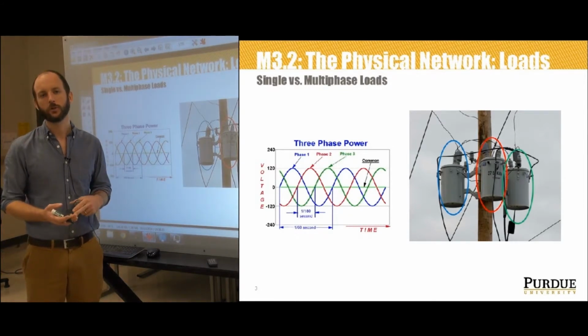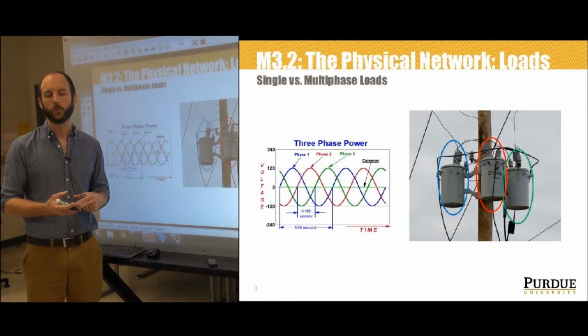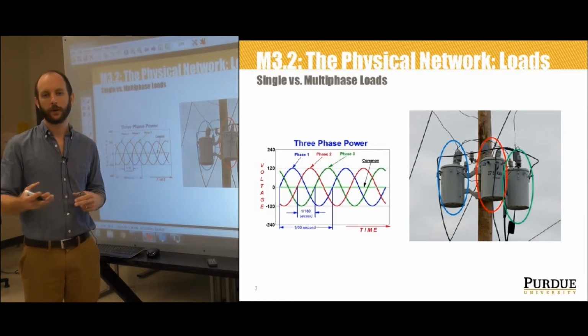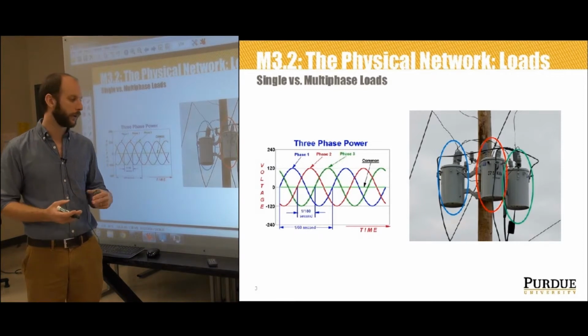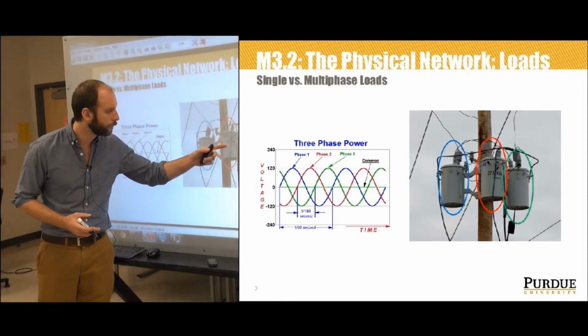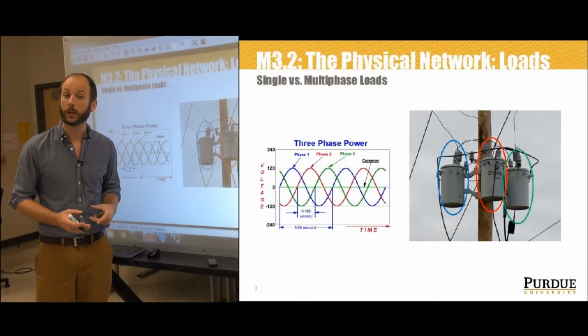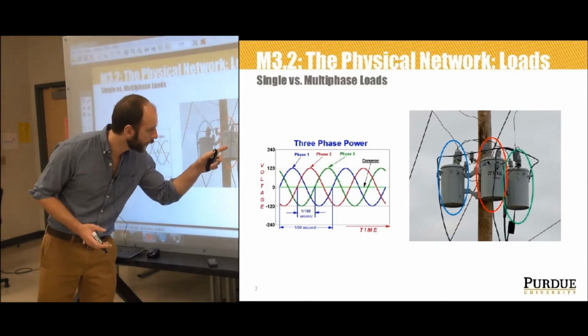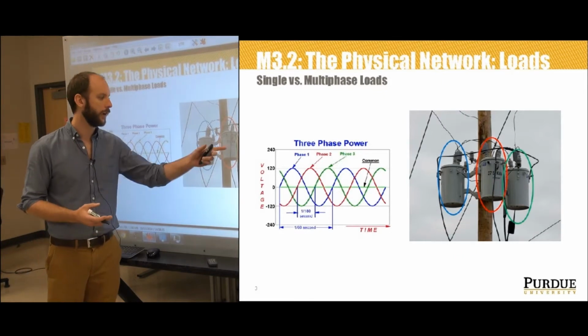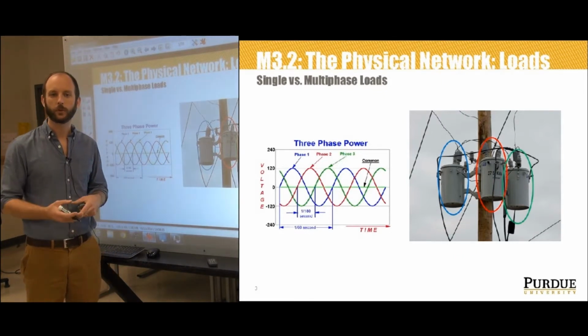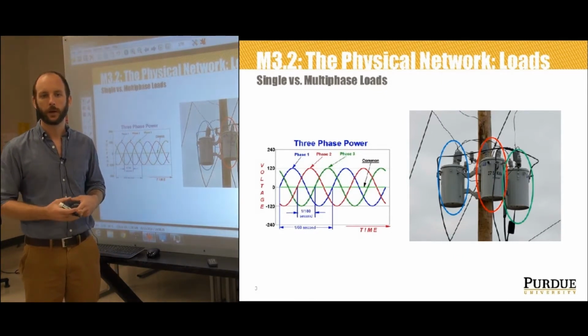In previous lectures, you learned the difference between real power or true power and apparent power, and we said that utility equipment is rated for apparent power because it's got to handle the current, right? So we look at this and we see on the outside of this transformer can that it says 37.5 kVA, showing that that single-phase transformer is rated for that much apparent power.